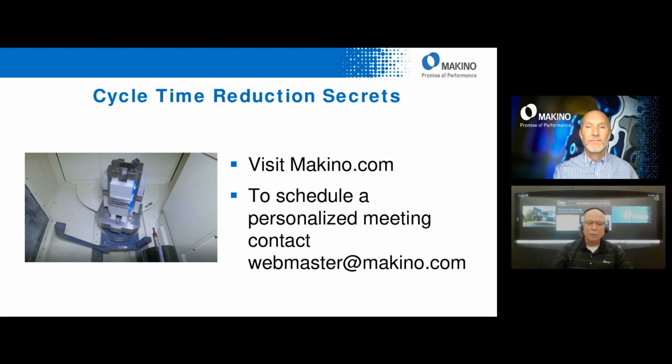The other way is automatically. We talked about that work data screen. You can actually assign to that pallet every time it comes in after a pallet change. It will measure that inertia. So that's one way you can do it automatically. There's a third way. You can insert a macro call in your CNC program using G65 P9880, and that calls the cycle as well. So there's really two ways to automatically measure that inertia on your pallet and on your Z-axis. Of course, right in the title of this webinar is saving cycle time, right? That's what this is all about.